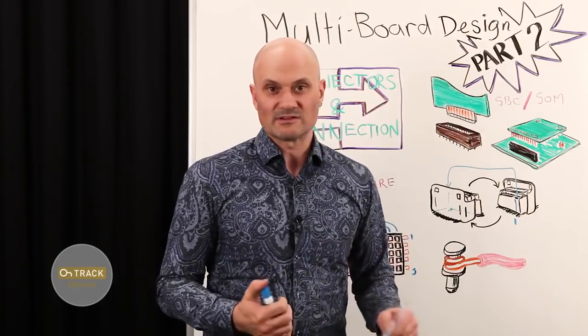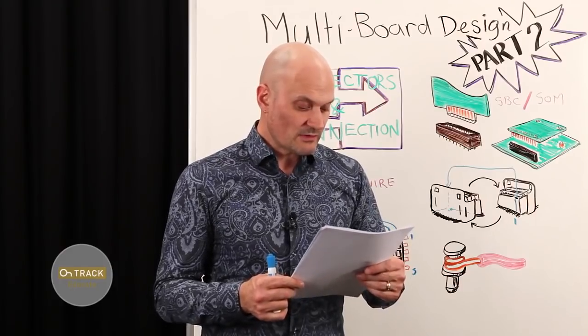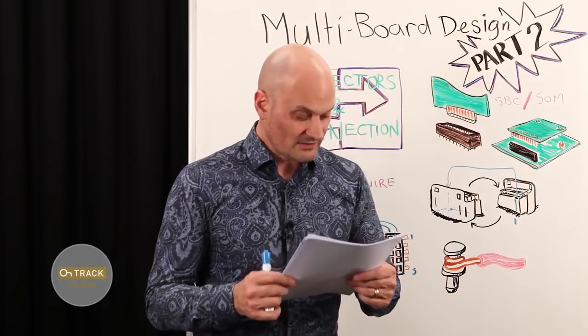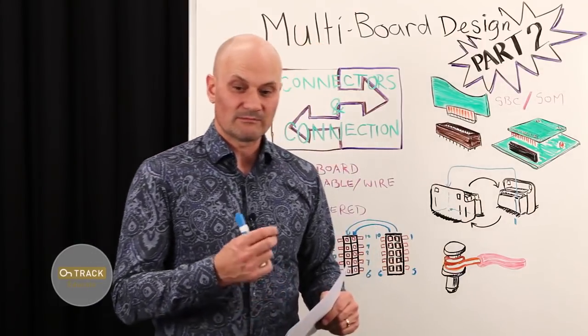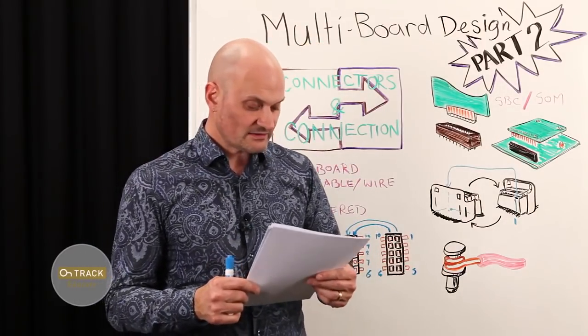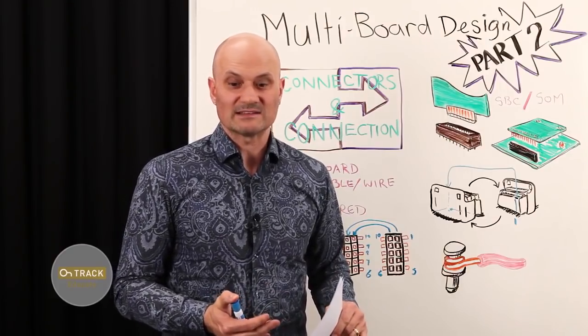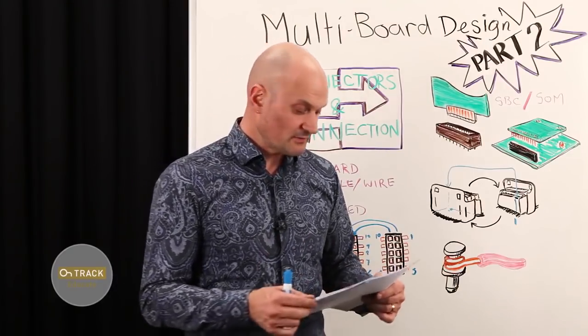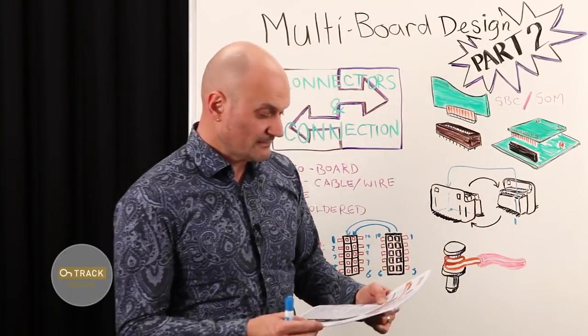So polyester is a reasonably high temp plastic as it is, but with the black glass, it's black, but with the glass fiber filling or glass crystal filling, it actually gives it a higher temperature tolerance and thermal mass for going through reflow. So I know that's going to work pretty well for reflow soldering.